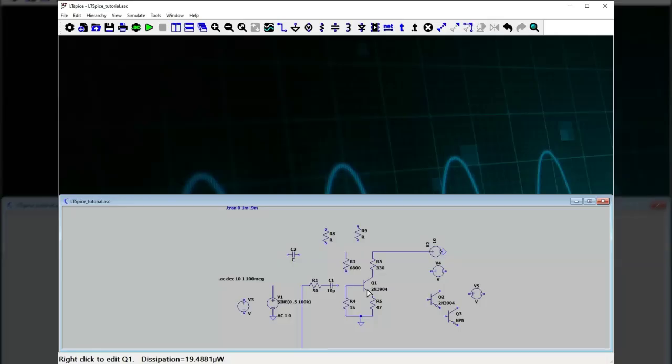So now I'm going to go get my scissors out, and we're just going to delete all this junk that we made here. You can't run a sim with a lot of floating nodes. It'll crash on you. So you have to at least partially wire some of this stuff up into something if you want to run it. If you want to run it and have it run.